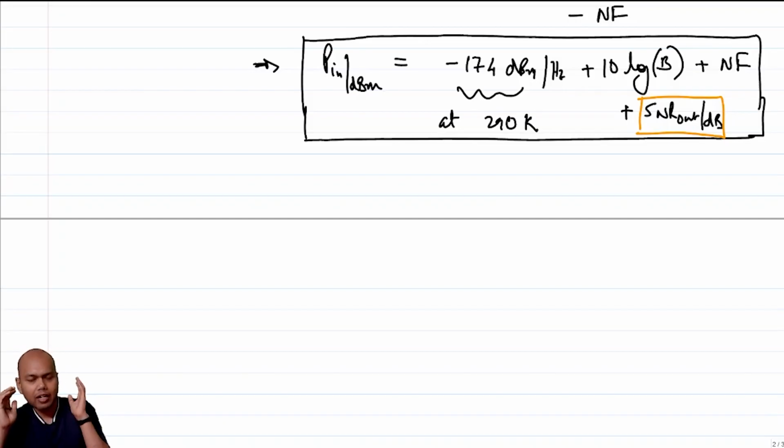I want at least 10 dB, or at least 20 dB, or at least 8 dB of signal to noise ratio at the output of your LNA or at the output of your system to at least make sense of what we are going to receive, and nothing gets drowned under the noise. Okay, so given that SNR out is a specification, this will be a given spec,